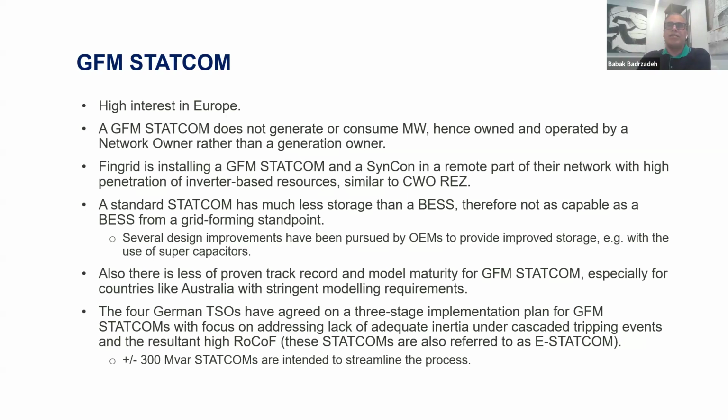There is a strong interest in having offshore wind in Europe with grid forming capability, but that's probably a matter of 3 to 5 years' time. And why is there a strong interest? Because some of the grids and grid codes are moving towards requiring grid formation at the shore side, which means that if you have back-to-back VSC HVDC, only one of those inverter or rectifier stations can be grid forming with current technology. The other one must be grid following.